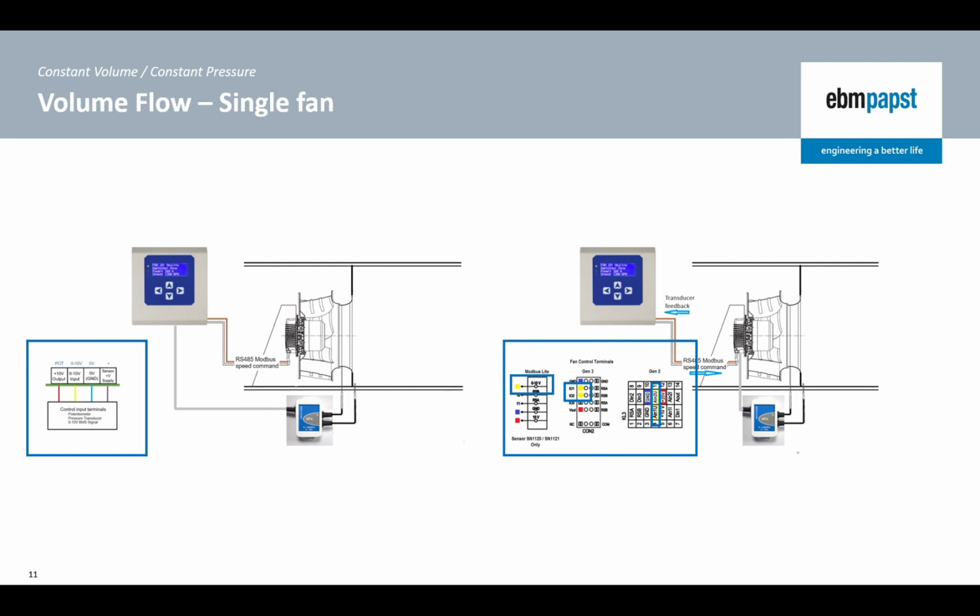For volume flow, the negative pressure port of the transducer should be connected to the inlet ring measurement tapping, and the positive pressure port should be connected to a measurement point in the suction side plenum. It is important that the measurement point in the suction side plenum is positioned in a still, non-turbulent area to avoid errors caused by the measurement of dynamic pressure.